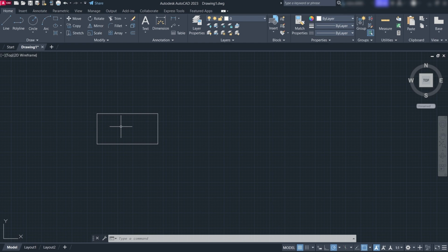Let's make a line or geometry using the polar coordinate system. In the polar coordinate system, we make lines which are inclined to a certain angle, called polar coordinates. Let's say that we have to make a simple line which is inclined to an angle of 30 degrees with a length of 5 units. There are a couple of methods for doing that, but we will use the simple polar coordinate method here.